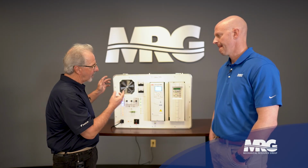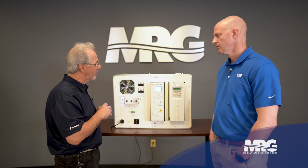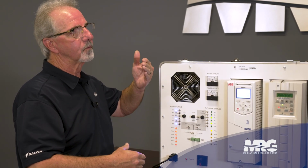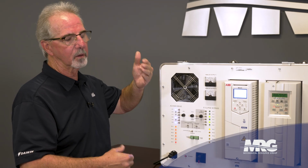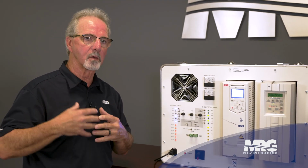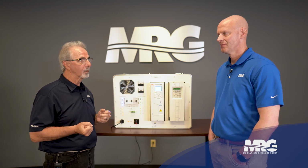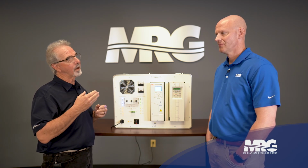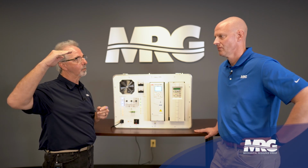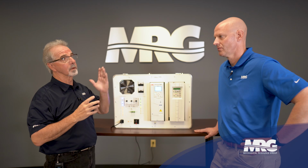Right now I get the input from the damper end switch on the smoke exhaust fan. Generally there's a transducer in there, and the transducer is feeding back what the pressure actually is. Now remember, when test and balance comes in, they measure how much air they require to get 30 pounds of pull on the door, and they know that 3.5 pounds is going to maintain 30 pounds, and that's why we put a weighted damper at the top of the stairwell that, if we get to 3.5, blows open.